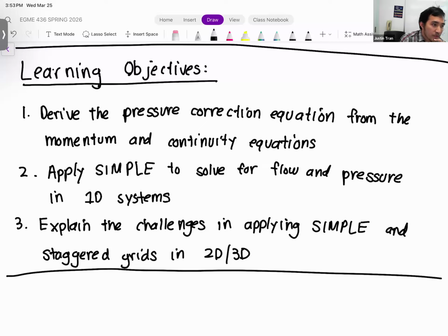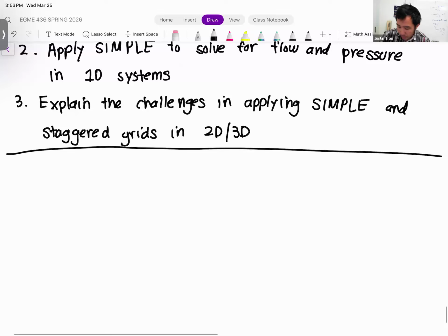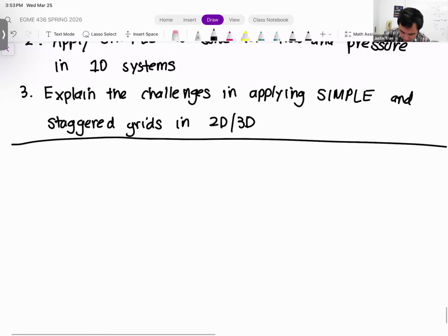Yeah. And on U, I pretty much assign a value to the right wall, and everything else as fixed, no boundary condition. And it still gives me issues in my controlDict after that. So the third problem, I think, is the one which is most involved because you have to do kind of two things. And so you do have to make a change to the blockMeshDict.